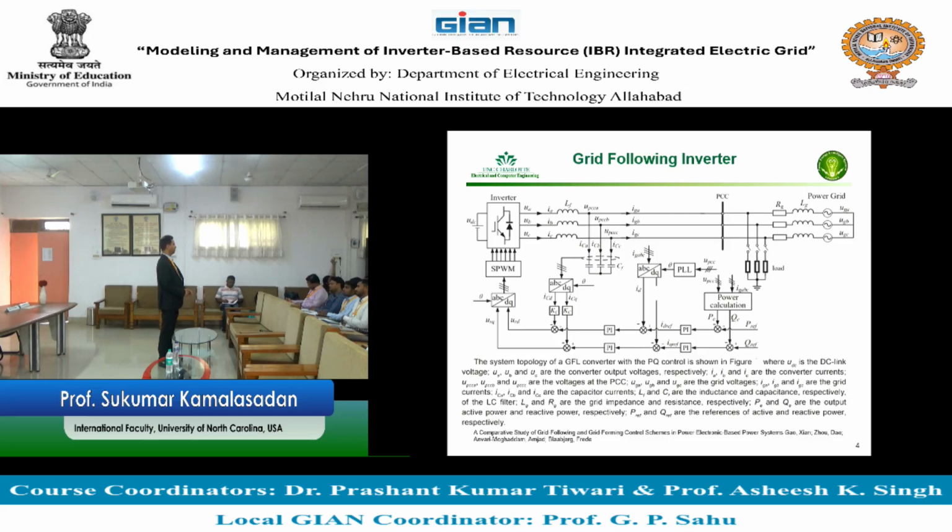The phase lock loop is actually not fundamentally done in electric power engineering. It is done in communication systems. Why is it used? It is used to lock a signal with respect to an oscillation. So for example, if there is an oscillation signal, we lock to this. That's the concept, and that concept you borrow. How the phase lock loop works, I will show you in a while. It is like a small controller to tap that.